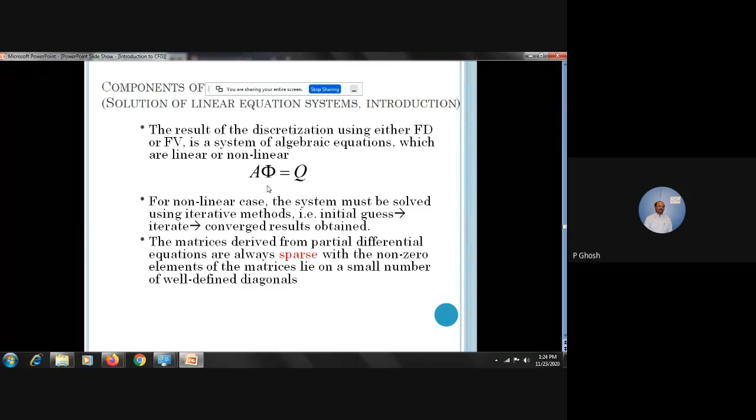First, you have to solve the coupled nonlinear partial differential equations. You only have 3 equations, so you have to introduce a 4th equation, which is continuity. Physically that is valid because of the law of physics, and you have to do that in a complicated geometry. So the normal Taylor series expansion may not work. You have to use finite volume or finite element techniques. Finite volume is popular because Fluent and all these packages are written using finite volume techniques only, because it can handle irregular geometry very easily.